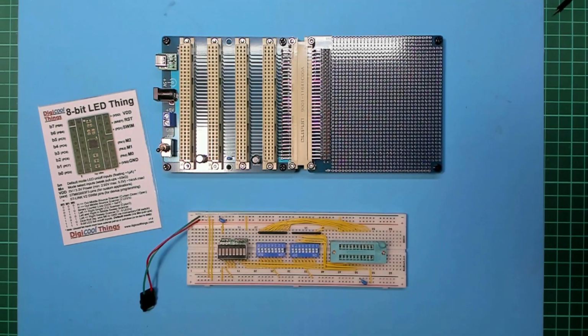In this way, when using an I/O board to experiment with different system configurations, it will be easy to just swap out the PLD for different memory map requirements. Of course, if building a more permanent system, you could just utilize a regular 20-pin IC socket.